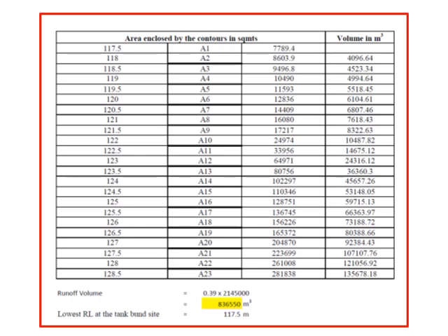So now the contour interval between two successive contours is 0.5. Therefore the volume is one third of the sum of A1 plus A2 plus root of A1 A2, close the bracket, multiplied by h, that is 0.5. So we get the volume 4096.